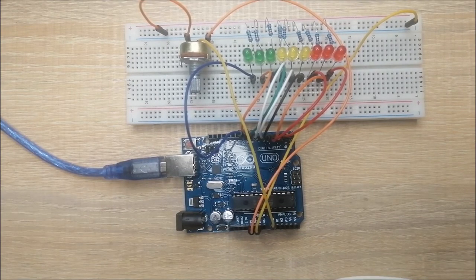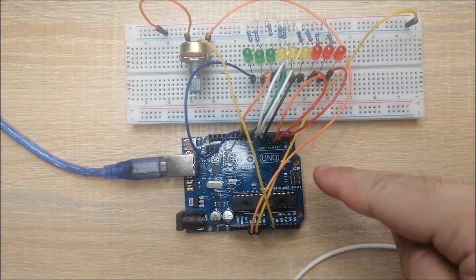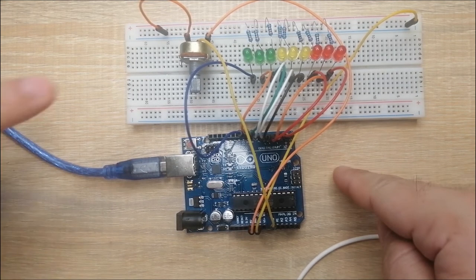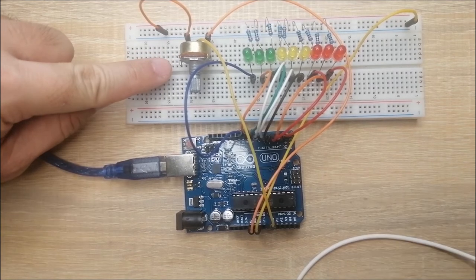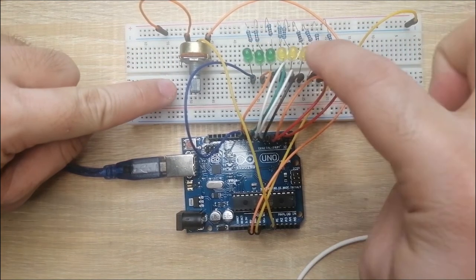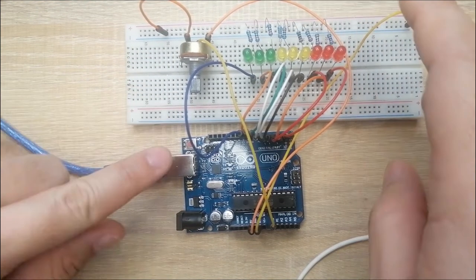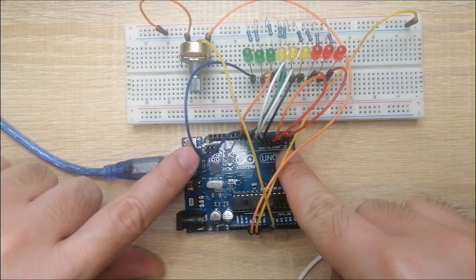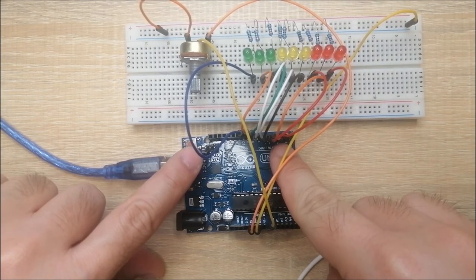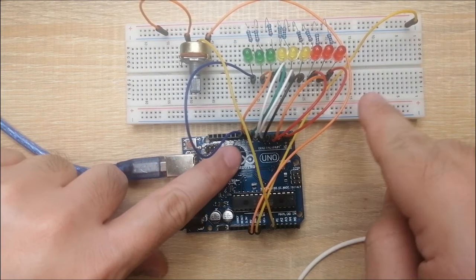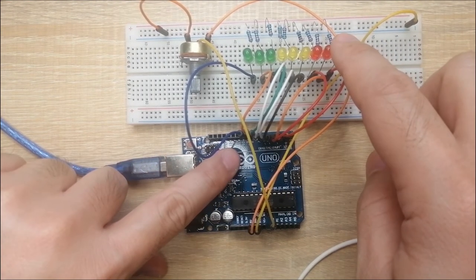Okay, so let's discuss how I wired up the schematics. So this is the Arduino Uno, and this is our potentiometer. The following are the LED strips and the current limiting resistors. As discussed, we just need to connect the pin values from pin 2 up to pin 10 to the LEDs,